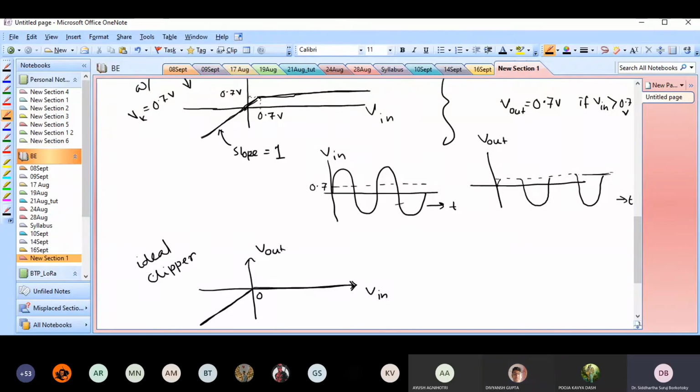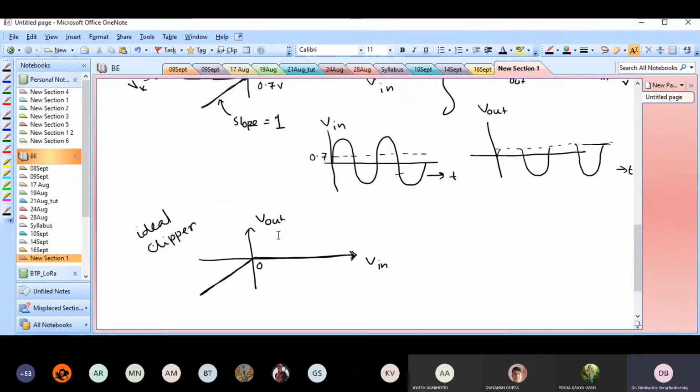So only an ideal approximation is applied. So this is an ideal clipper in that sense. But you could have a diode for which you are applying the second approximation, fine. But you could actually add a DC bias of minus 0.7 volts to make the diode have the exact same transfer characteristic that we are calling an ideal clipper in this case.